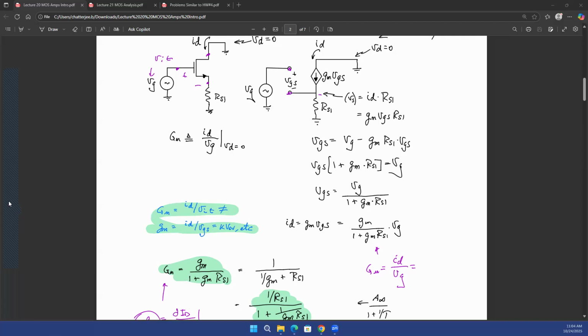That you had an input coupling capacitor, an output coupling capacitor, and a bypass capacitor for this source resistance in your exam question. And it is asked, what kind of filtering does it do? Of course, it will be a high-pass filter, because at lower frequencies the capacitor is open, so it has no effect. At higher frequency, it shorts the source to the ground, so your gain improves.